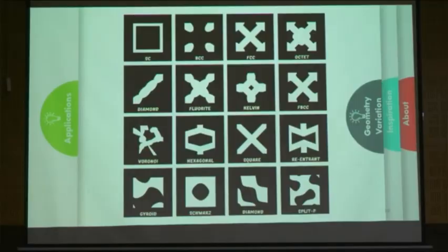Lattice, frankly speaking, since we don't have a device to measure the roughness, we didn't measure it. But the thing is, it is a very rough surface. Using post-processing we have improved the surface, that we can say, because we have seen that the powder intact with the lattice gives a rough surface. And we applied sandblasting.